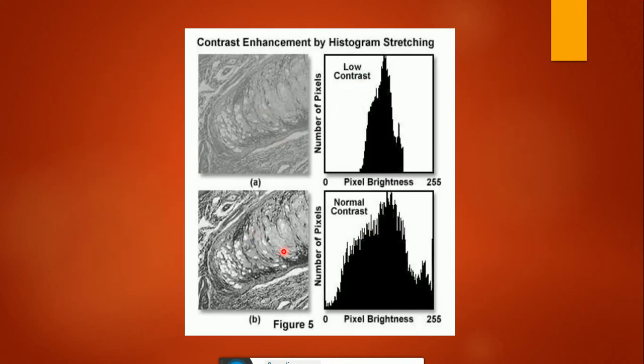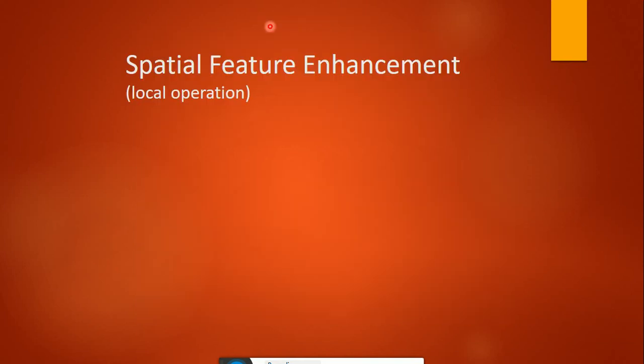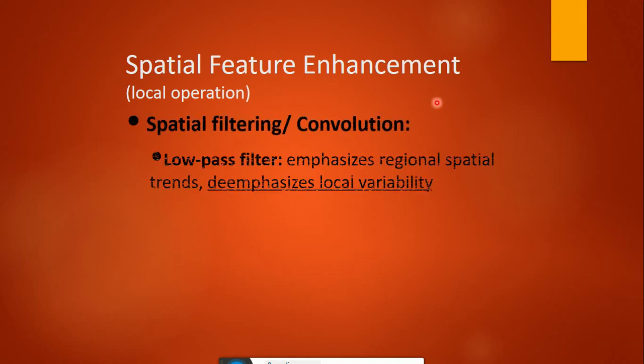High pass filter image: the convolution matrix is 11 by 11 pixels. We put this image with the matrix moving in the northward direction to the southwest direction. Directional filtering from a different direction tends to enhance or disclose linear features that lie preferentially near perpendicular to the traverse direction. In the image below, the array was moved diagonally across the scene.